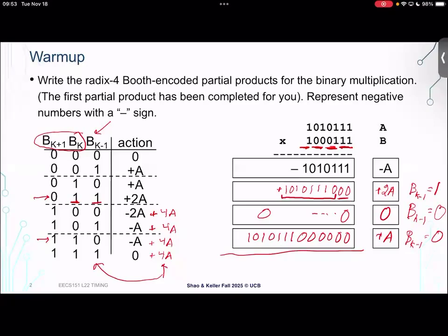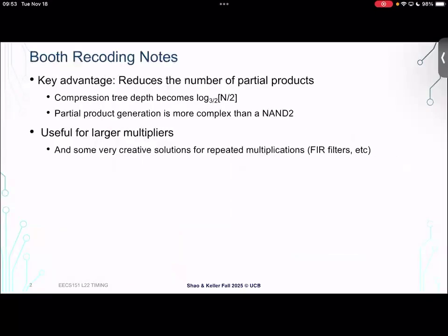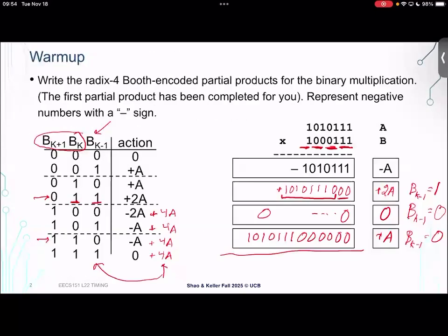So, and as an aside, if there are places in, say, your processor design where you're multiplying by a fixed amount, and that fixed amount happens to be a power of 2, you can just do a shift instead, right? You can skip this whole exercise of having to design a multiplier in the first place. So this is a very common trick, to try and do shifts instead of multiplies because it's so much cheaper.